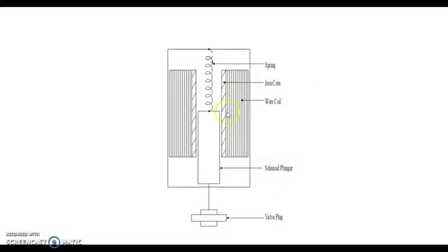By means of an amplifier, this change can be made strong enough to activate the control devices. Again, the magnetic field in the solenoid can be influenced by an iron armature in a coil. By moving the armature up and down, activated by a sensing element, a change in current will occur. By means of an amplifier, the changes can be made strong enough to activate control devices.